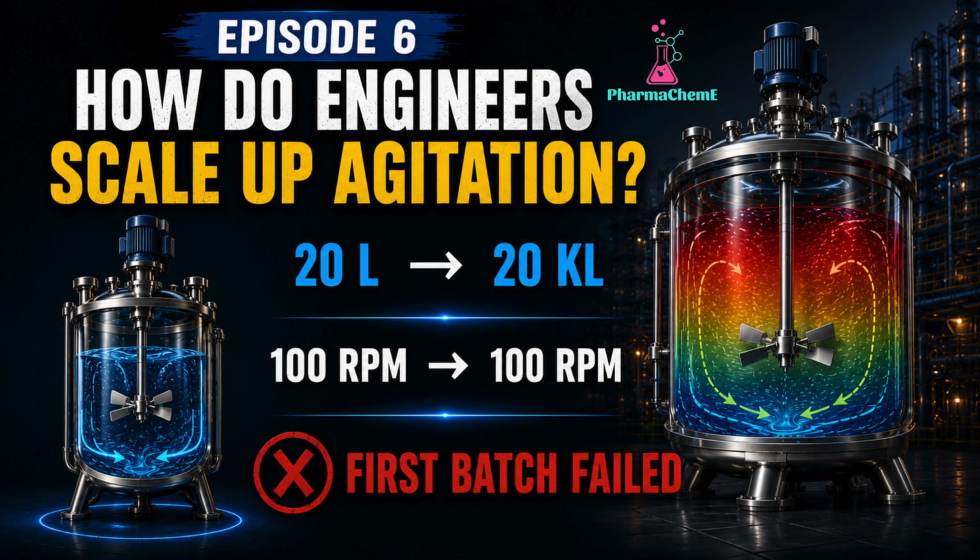Imagine you've successfully developed a process in a 20-liter laboratory reactor. The reaction proceeds smoothly. Mixing is excellent. The product meets every quality specification. Now it's time to manufacture the same product in a 20 kiloliter production reactor. To keep everything the same, you install the same agitator, and you also keep the speed at 100 RPM. Everything should work exactly the same, right?